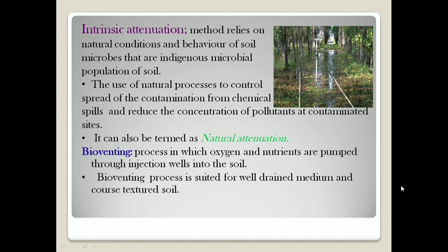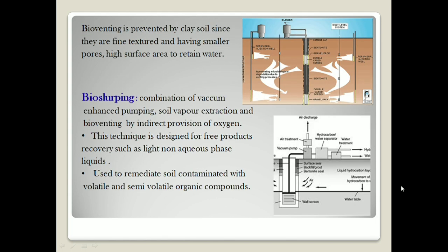Bioventing, the process in which oxygen and nutrients are pumped through injection wells into the soil. This bioventing process is well suited for drained medium or coarse textured soil, whereas the bioventing process is prevented by clay soil, since it is fine textured and possesses smaller pores and a high surface area to retain water.